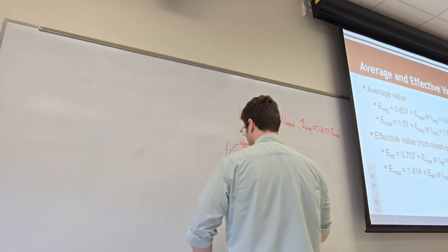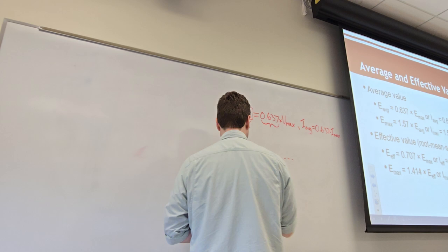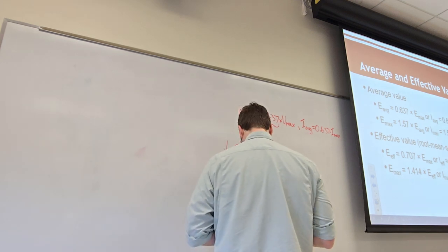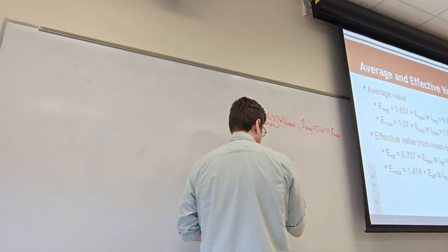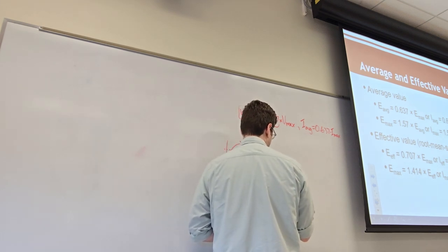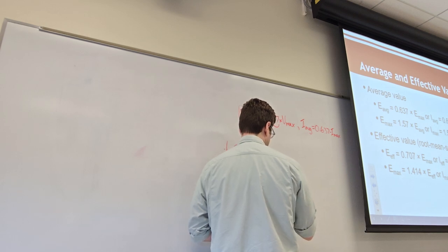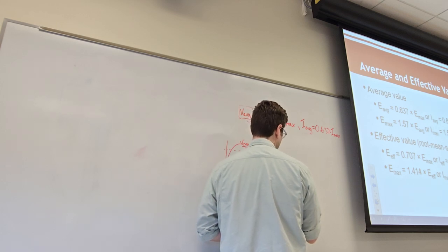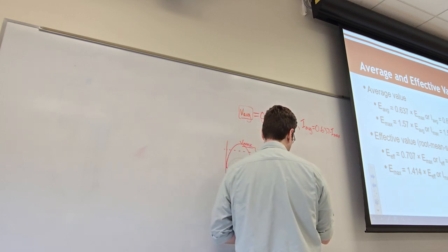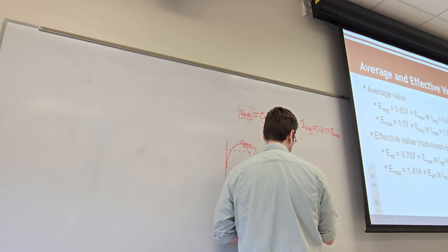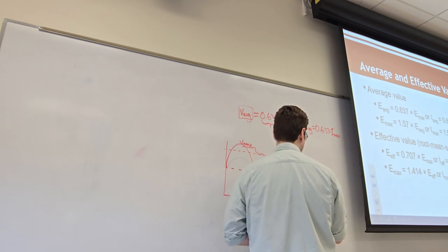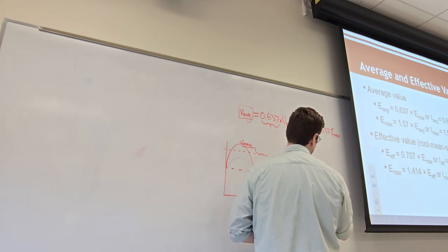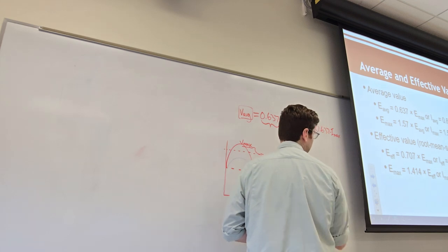Okay, likewise for the current, that occurs over that same interval, right? The amount of current that flows as a result of that voltage can also be talked about in terms of its maximums, minimums, whatever. This is just the maximum in one current direction or the other, and that is the same thing. So the way that you convert Imax or Vmax into average is with our magic 0.637 number.